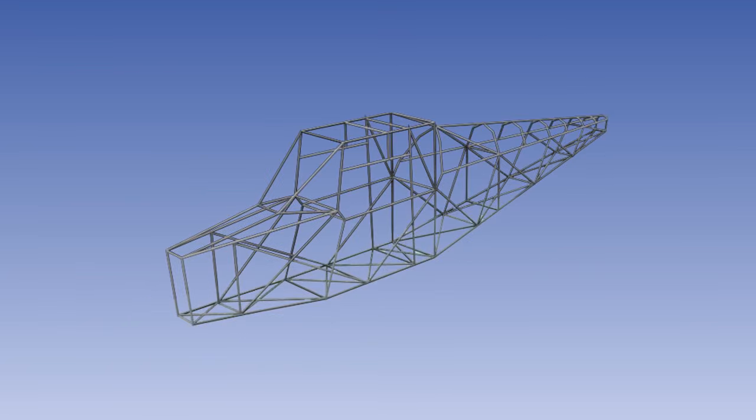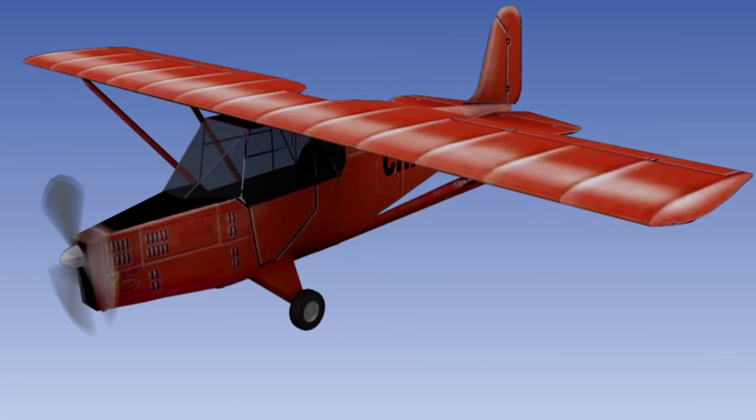The framework or truss consists of light gauge steel tubes welded together to form a space frame of triangular shape to give the most rigid of geometric forms. Each tube carries a specific load, the magnitude of which depends on whether the aircraft is airborne or on the ground. It is a strong, easily constructed, and relatively trouble-free basic structure. The framework is covered by a lightweight aluminium alloy or fabric skin to give an enclosed, aerodynamically efficient load-carrying compartment.